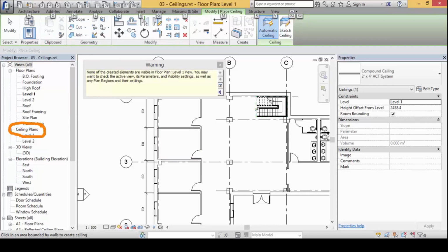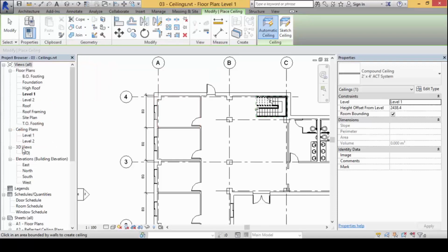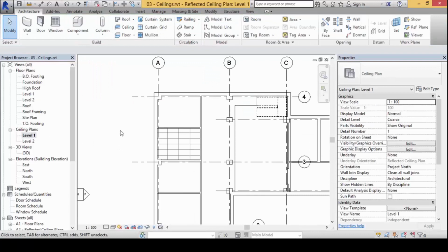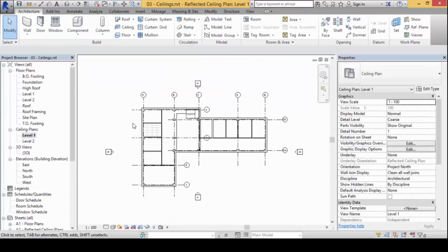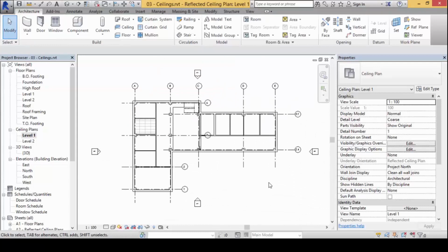You should technically, before you even start, think, okay, I need to work on the ceiling. First thing you do, you should be looking at the ceiling plans, opening up the ceiling plans here. We are very, very used to the term reflected ceiling plan. By right, it should be labeled as reflected ceiling plan because of the reflection, but it's flipped so that it orientates nicely. That's the thing. Actually, it's been created, it's here, but we just don't see it on plan, because it looks downwards, that's all.